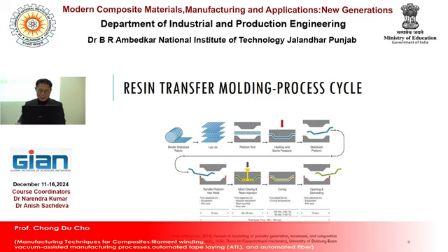If we think of the full cycle of the resin transfer mold process from the raw material, the layup is needed first. This is a kind of preform, right? So this preform tool is fit into the mold, and the cavity will capture the layup of fibers.